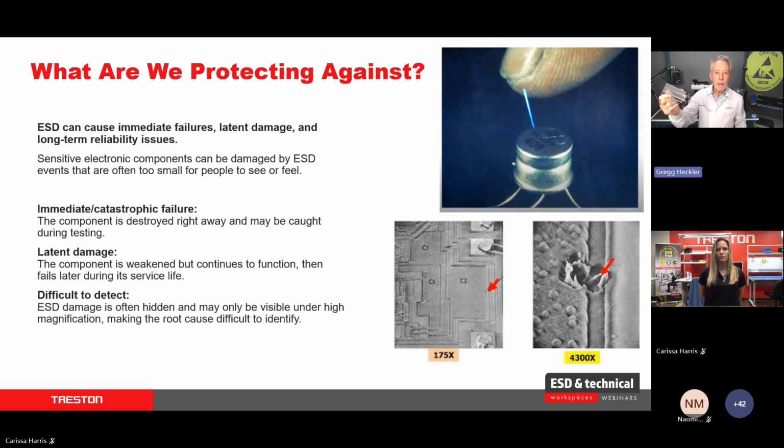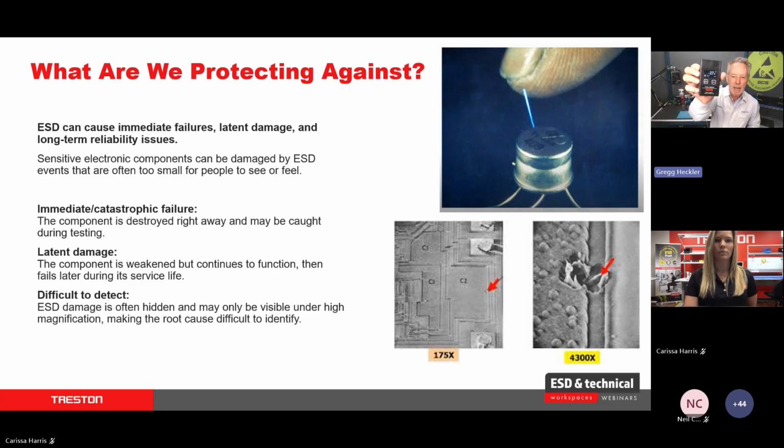They could be the fiberglass PCB itself. It could be a connector. It could be, let's say you have a Samsung cell phone. The case of a Samsung cell phone is plastic. It's an insulator. So those are the things that generate the charges and the greatest charges out there. This represents an isolated conductor, or you not grounded, wearing your wrist strap, or let's say the IC sitting upside down on the workstation with the leads facing the air. So the way we generate static electricity, and I've also got what we call a static field meter here.